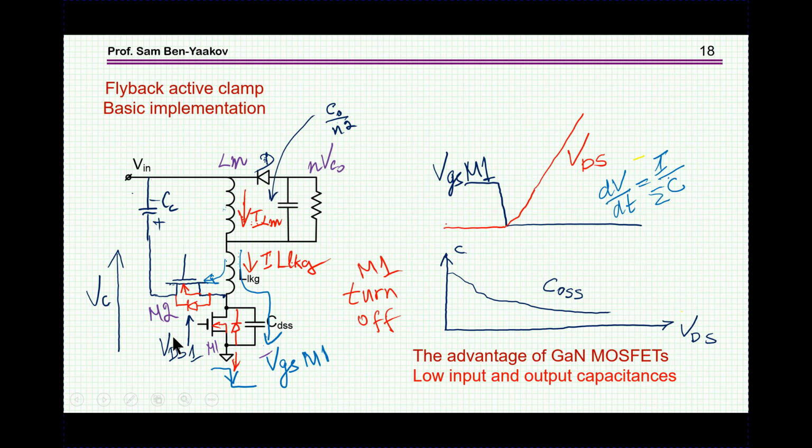Somehow Murphy missed the situation, and we are saved here. Luckily, the capacitance of a transistor at the very beginning, at very low voltages, is very high. So we have a relatively high capacitance, which slows it down.